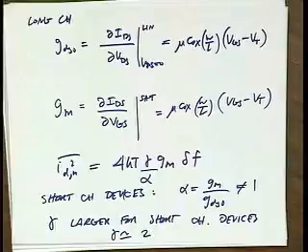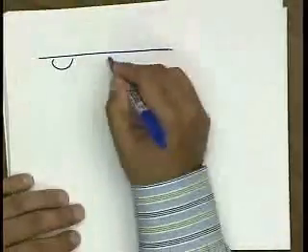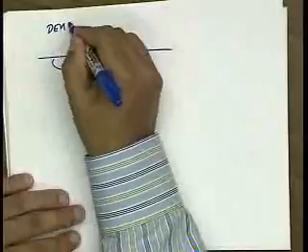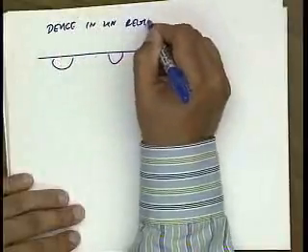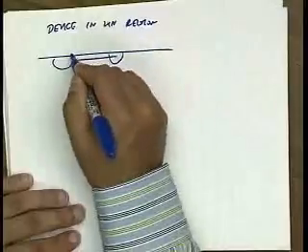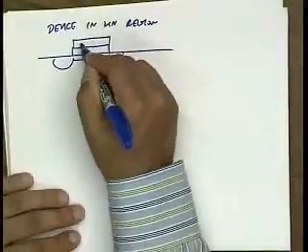Too much gain. So the channel resistance, it's also not a physical resistance. No, it is a physical resistance. Yeah. Because a channel is just an inversion layer, right? Think about it this way. When I put my device, let's say a device in linear region. So let me turn the device on.